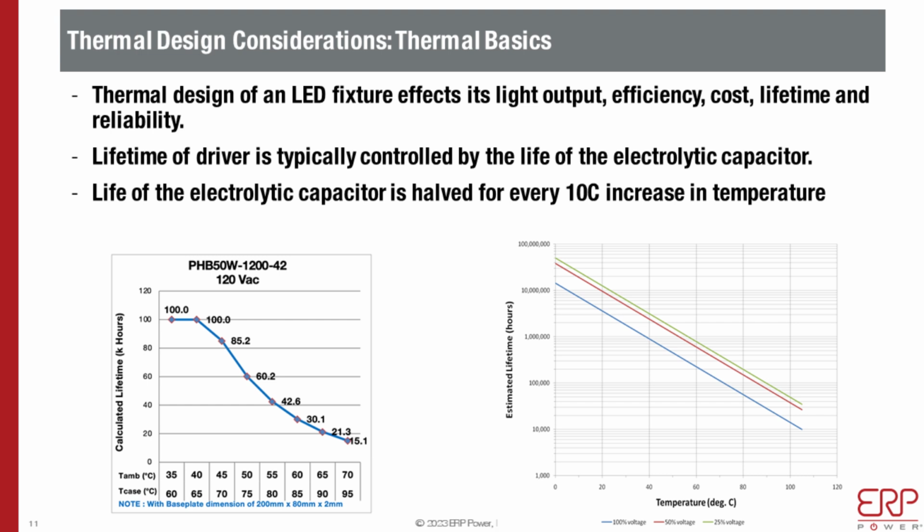The lifetime of a driver, which exists in our modules, is typically controlled by the life of the electrolytic capacitor. Think of it as there being a little bit of moisture in the capacitor. If the temperature is high, that moisture makes the conductive material inside, where the charges pass back and forth from positive to negative, degrade, and after a while your system is going to malfunction. And that is how the lifetime is defined.